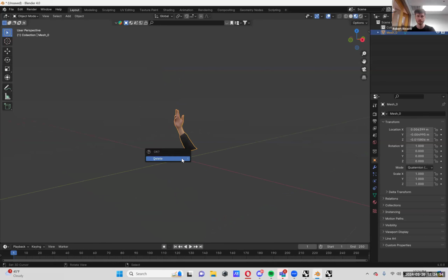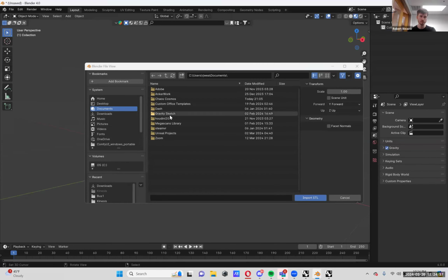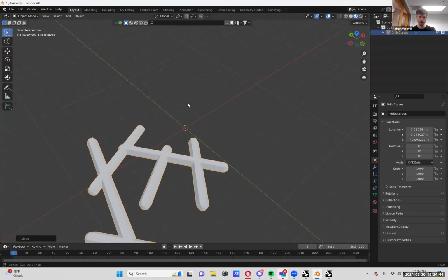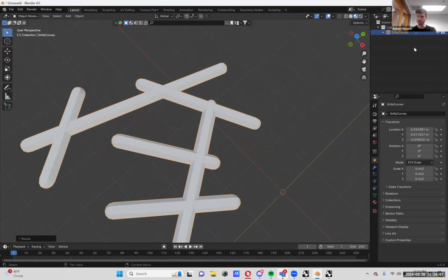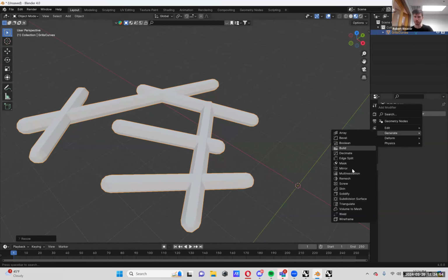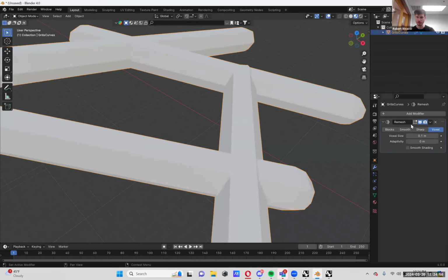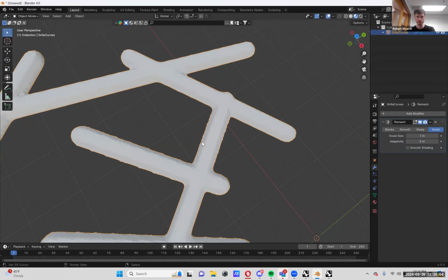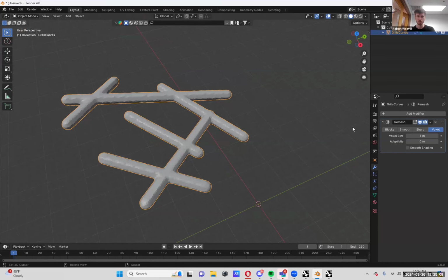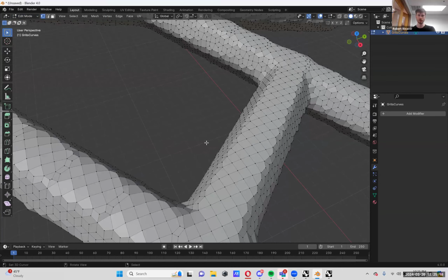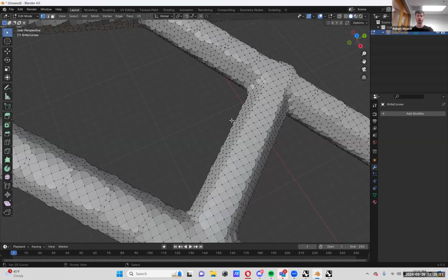Okay, so now we're in Blender. And this is recording because we maybe have to go back to this later. But what we can do is really quickly use the remesh tool, which is basically Dendro, to union everything together pretty quick. So that took it from being separate shapes to now being one mesh. So we can apply that. And now if we go into edit mode by hitting tab, we can see that all the vertices are now one, so we have a single mesh.